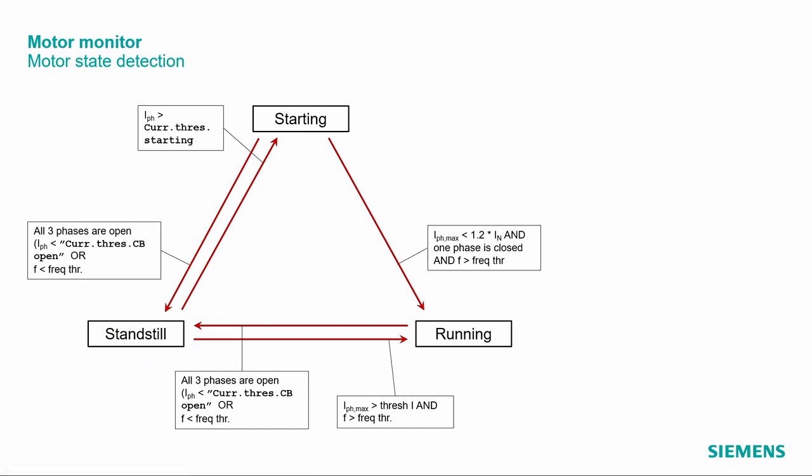When we have, for example, a high-speed busbar transfer, or a certain interruption of the voltage due to problems with the in-feed, then at a time when the motor is not powered anymore, it will slow down, often relatively fast, because there's a load behind the motor. When the voltage comes back, it accelerates. And in that case, we need to understand that the motor was not running all the time, for the load jam protection function we see later. Therefore we have here these frequency criterions and other criterions.